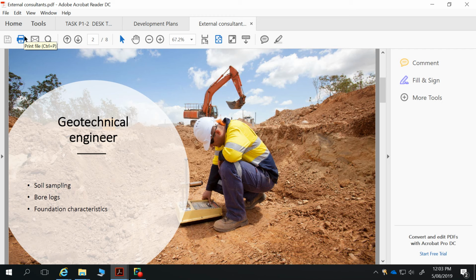Beneath that, let's say we've got clay with small sandy pockets. Then we'll have clay with weathered rock fragments, and under that maybe sand, weathered rock fragments, and small pockets of clay. As we get deeper and deeper, we get that information about what's in the soil. Across the top of our table we'll have borehole number 1, borehole number 2, borehole number 3. Those horizons may be different for each borehole. Let's have a hill here like this. We've got our first horizon, our second horizon is doing that, our third horizon is doing this.